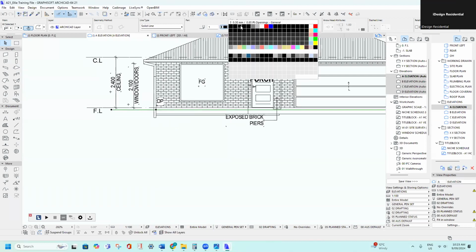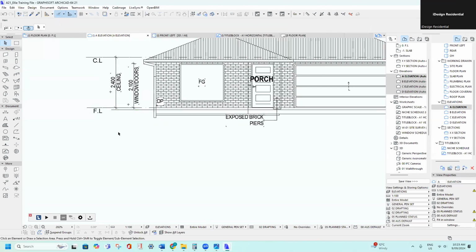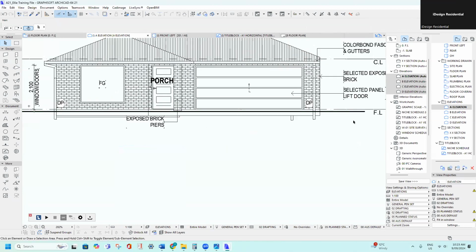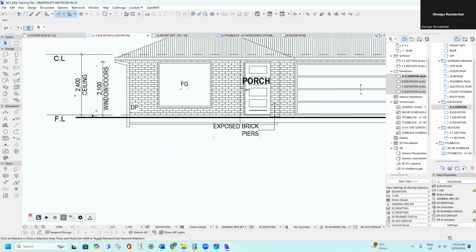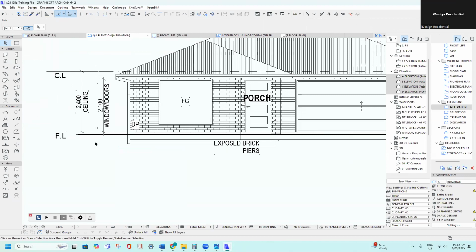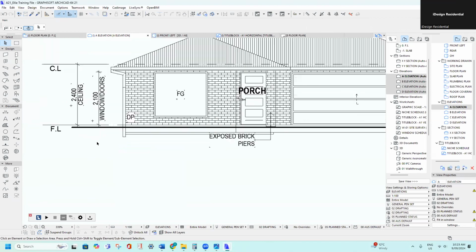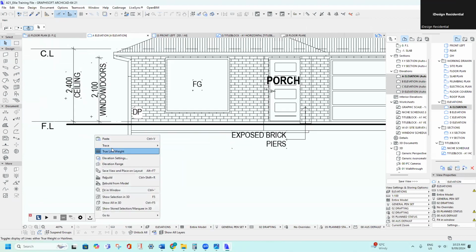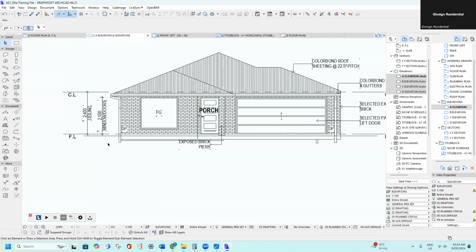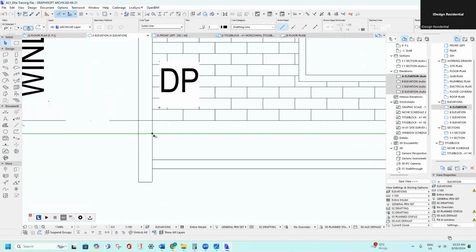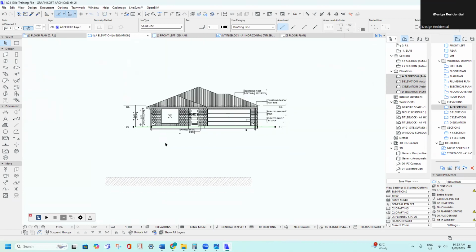And then I change that line work to 0.5 millimeters, so it's more distinct. So if you right click, true line weight, you can see it's a thicker line. So when it gets printed, it's more visible. So it shows you the ground line. When I'm actually using CAD, I like to take off the true line weight most of the time, just so that it's more fine. You can get into the detail a bit easier. You can see more.